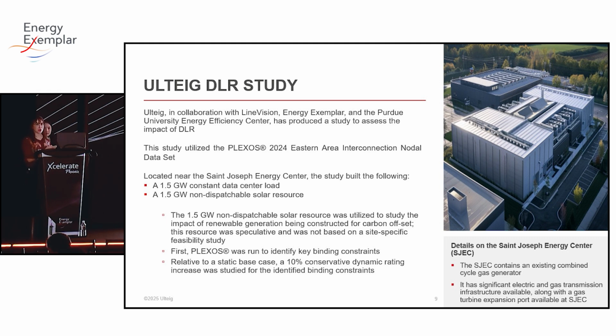So we have the data center load built in, and we also have this solar resource built into the 2024 EIC data set. From there, we ran the simulation to identify some key binding constraints. The lines where those binding constraints were identified had the conservative static ratings that just come as default within the PLEXOS data set. So from there, we added a 10% dynamic line rating to that static value for those lines where we found the key binding constraints. We then monitored those lines to see if increasing that line rating would have any effect on the system.